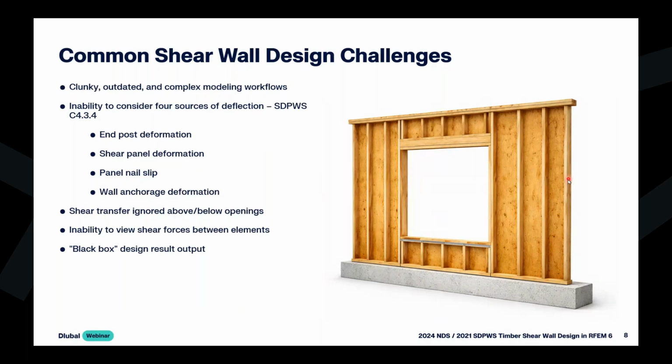We also want to consider the shear panel deformation, so we're talking about the sheathing itself. Then the panel nail slip. In the SDPWS code, this is a nonlinear equation that's given. And finally, we have the wall anchorage deformation, so we're talking about those hold downs and those shear connectors that we had shown on the previous page.